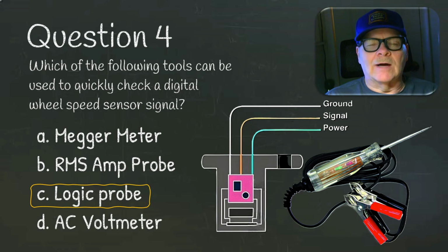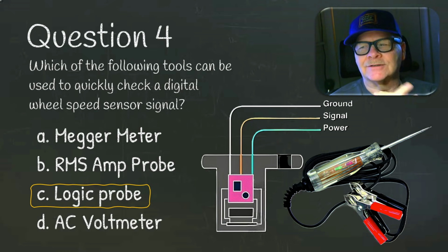That's typical. When I was working at the Ford Jeep dealer, right after these electronic wheel speed sensors came out, there was a Jeep Grand Cherokee that came in that had these electronic sensors on it. We had never seen those before. I found a code for a wheel speed sensor, and I just decided to go ahead and swap with another wheel. I put the wheel speed sensor from a different wheel on that one, and the code moved with the sensor, so I knew it was a sensor. It was just a real quick thing I came up with.